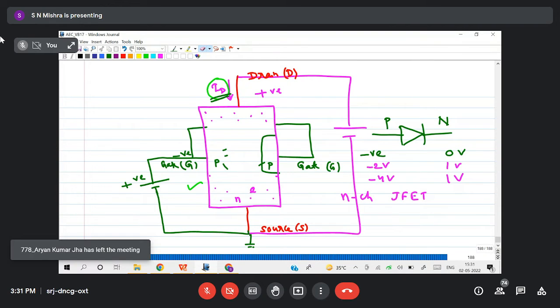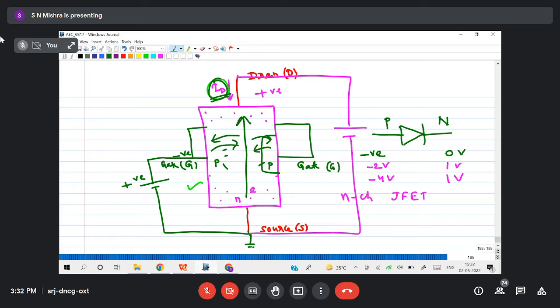Yes, sir. Okay. So there will be no depletion region, which means the holes which are present here can easily move to this side, and the electrons on this side can easily move to this side, right? Yes, sir. So can I control this current? No, sir. The carriers which are moving from here, can I increase or decrease them depending upon this voltage?